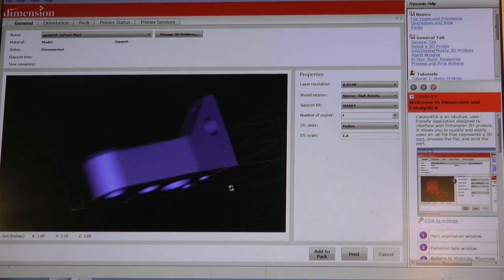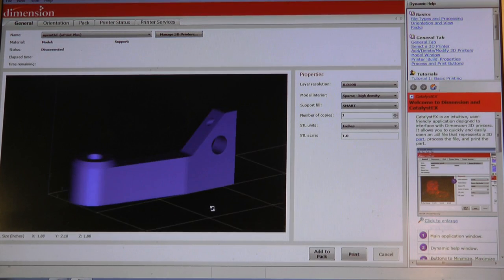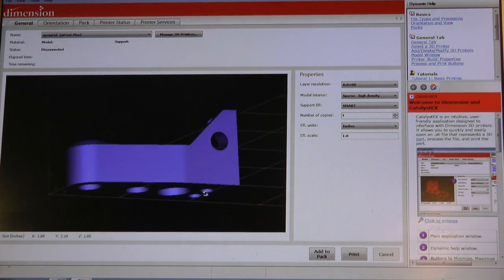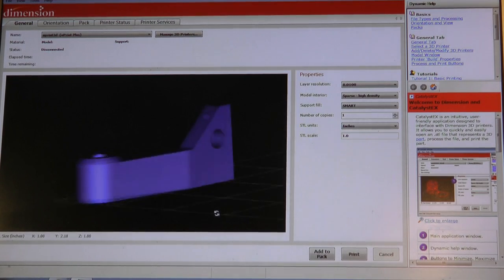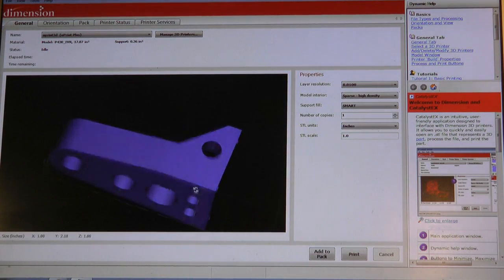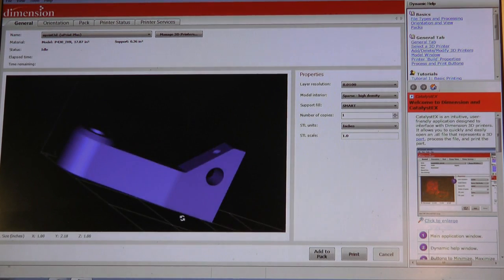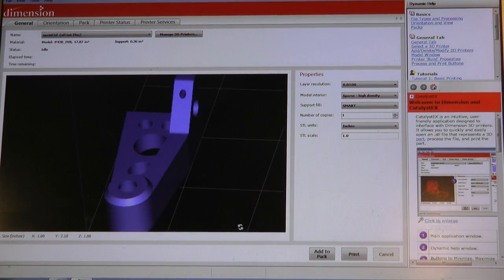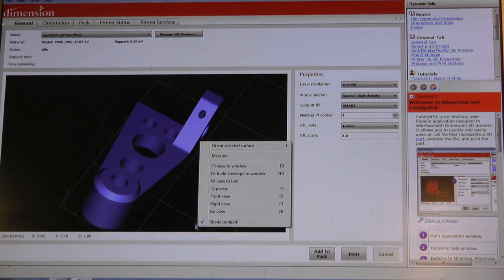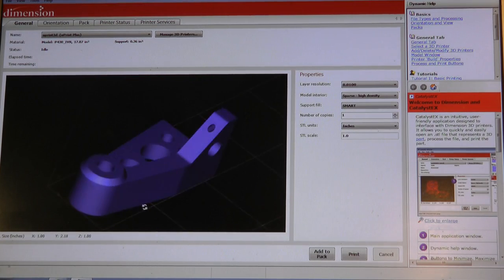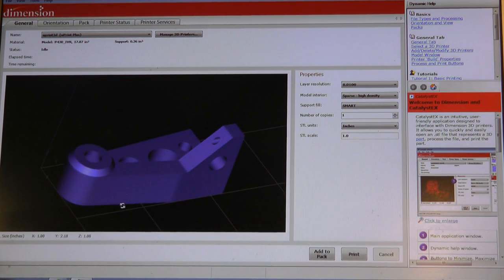It infers an orientation for the part. It's going to build the part from the bottom up, and right now it's got that part down, which is good. I will let it build that way. There are different considerations for the build orientation in terms of the strength of the part, the accuracy of the geometry, and how much support material is generated for overhangs.